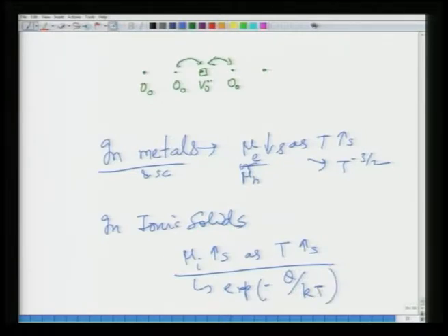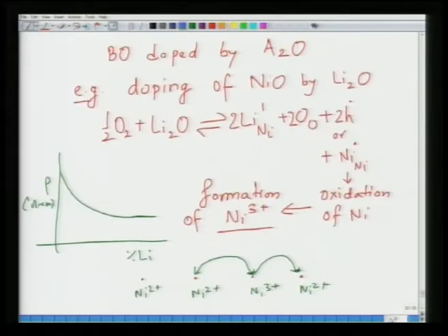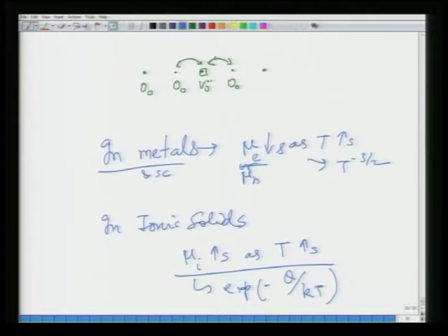So, this you can imagine as if you have counter movement of vacancies, because a charge is associated with the vacancy. In the previous case you can say it is the movement of Ni3+ ions. In this case it would be a movement of vacancies. So, instead of charge transport you must consider this rather as an ionic transport. That is why conductivity in ionic systems is a hopping kind of system, because here the defects move, and movement of defects is nothing but diffusion.